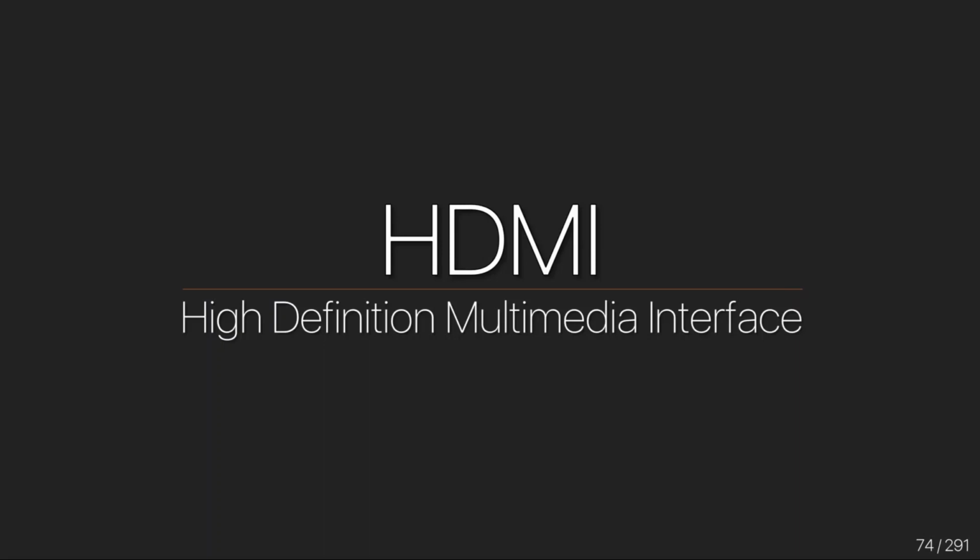So it's not required. But you have these Y cables, these breakout cables. You have DVI on one end, and then it breaks out to DVI-D and then the VGA. In those cases, the DDC is usually connected to the DVI side, so it's not connected to the VGA. In some cases it is connected, but if you connect two sources, then they can mess up the communication because three devices are trying to communicate. So it can be, but it doesn't need to be, basically. All right, carry on.